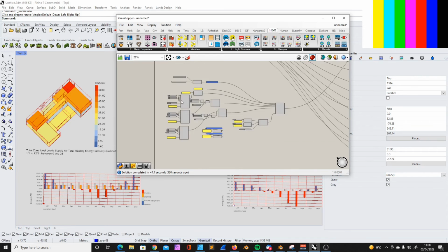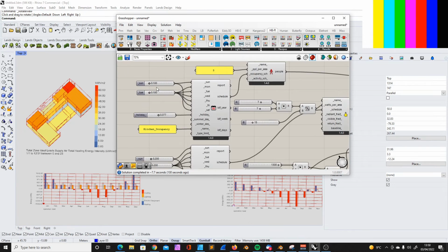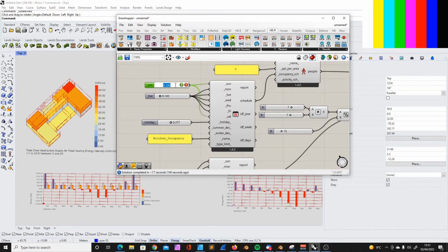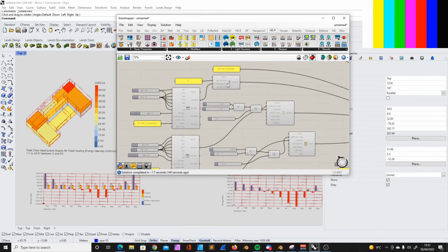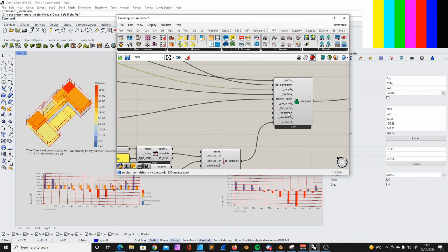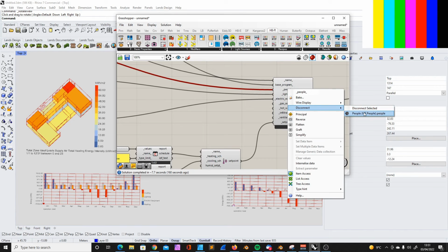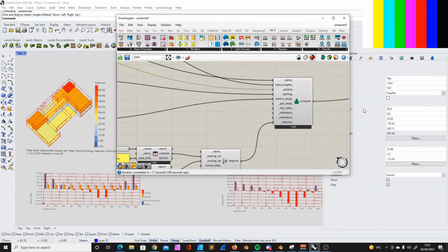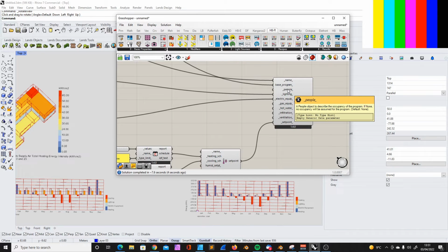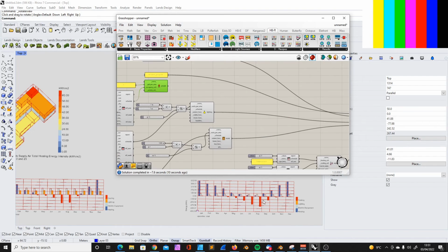I guess it's not how heating and cooling works. It also changes a lot with the occupancy schedule, so if that is set differently, then I also get different results. For example, if I set all these to fully occupied, the people also create some heating, which has an influence on the cooling and heating. If I remove that completely, it's interesting what's going to happen. Yeah, it has quite an influence. Then it assumes a generic default value.